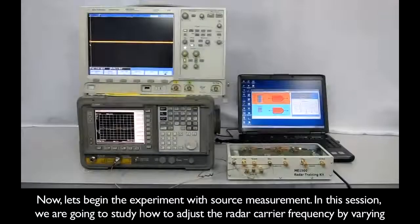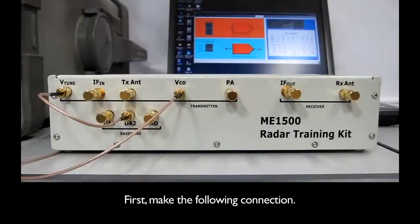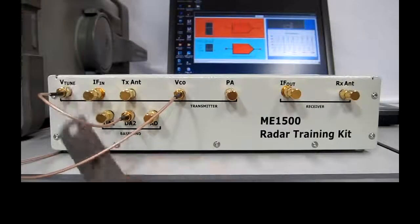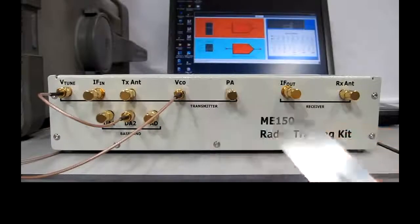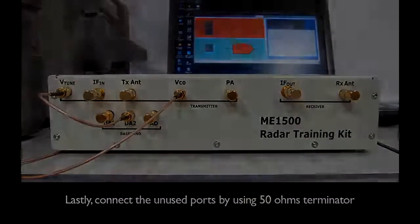Now let's begin with the experiment with source measurement. In this session, we are going to study how to adjust the radar carrier frequency by varying the tuning voltage using radar waveform synthesizer software. First, make the following connection. Connect the DA2 output port to the VTune port. Connect the spectrum analyzer to the VCO port. Lastly, connect the unused ports by using 50 ohms terminator.